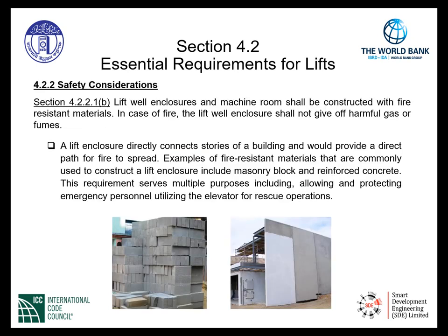Safety considerations is indicated in section 4.2.2. As we move through this particular section to item B of section 4.2.2.1, there is a requirement that lift well enclosures and machine rooms shall be constructed with fire-resistant materials. In case of fire, the lift well enclosure shall not give off harmful gas or fumes. A lift enclosure directly connects stories of a building and would provide a direct path for fire to spread.